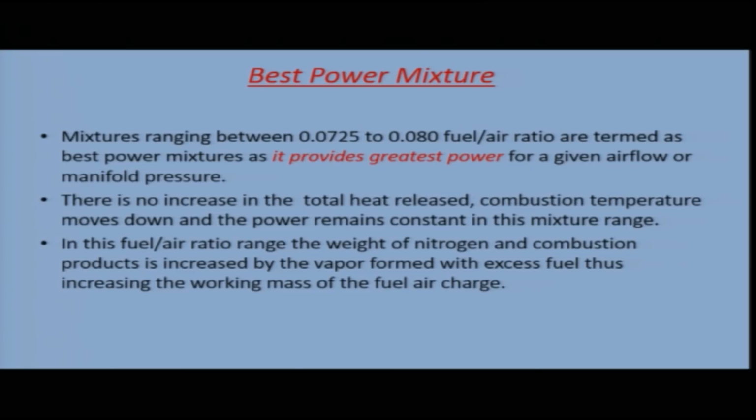Mixtures ranging between 0.0725 to 0.080 fuel air ratio are termed best power mixtures, as they provide the greatest power for a given airflow or manifold pressure. Now, for a given airflow or manifold pressure, this ratio is providing the greatest power. So, this is termed the best power mixture, since you are getting the greatest power for a given airflow.